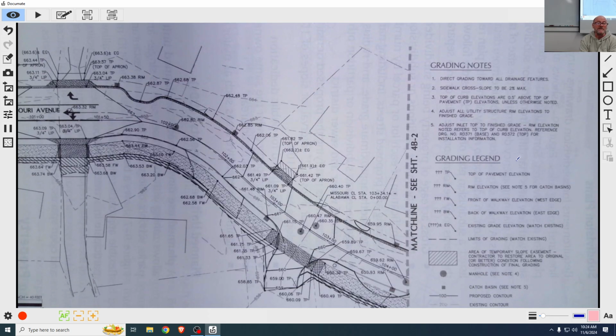Well, in that case, 2% slope. Yeah. So if it goes from the middle and it crowns in the middle, like for drainage, which is fine, then it can't be like half of that because half that height. So for 8 feet wide, it can change from end to end no more than 16 hundredths of a foot, which is like 2 inches.